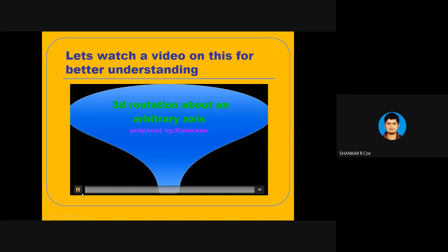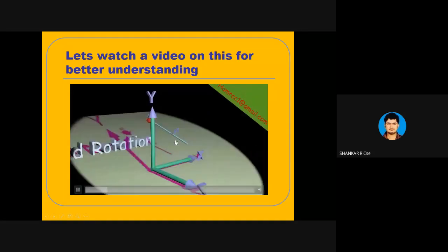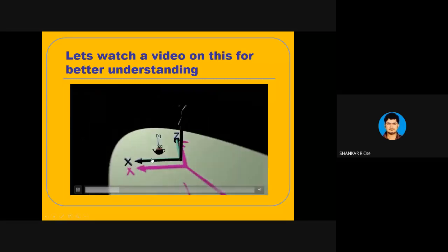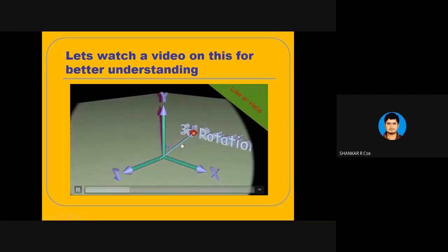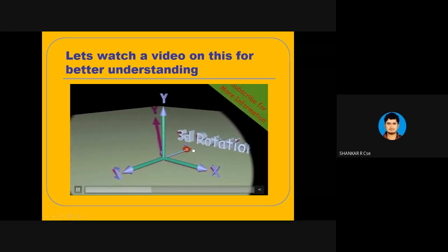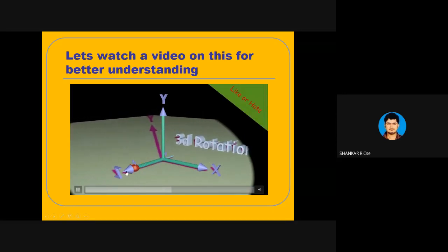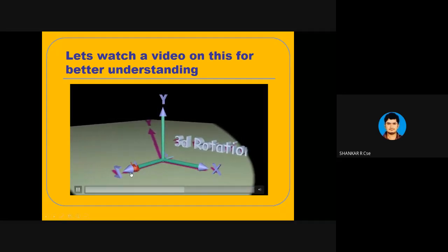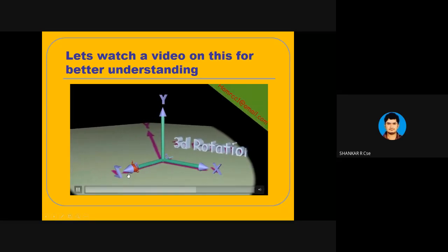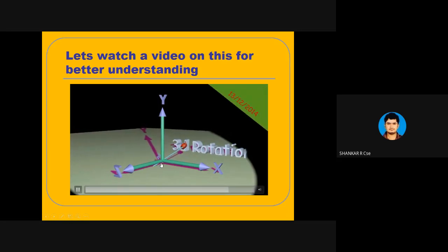You can see here, there is this arbitrary axis. The teapot is your object. You can see that it is neither parallel. First step is bring to origin. Second step is put it to the z-axis. Third step is rotate the object with respect to the z-axis. Fourth one, rotate the arbitrary axis back to the origin. Fifth one, go back to wherever you were.